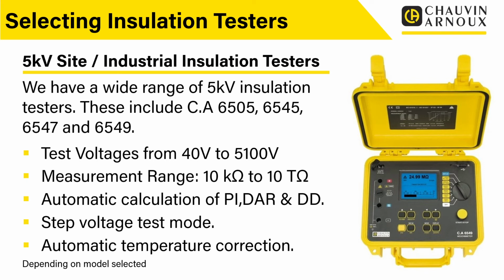As I spoke about before, we've got the ability to do the PI, DAR, and dielectric discharge test, the DD tests. But these are automatic. They're automatically calculated for you, so you don't have to do this manually. And we can also do the step voltage test on the 6549. We can actually perform the step voltage test automatically.